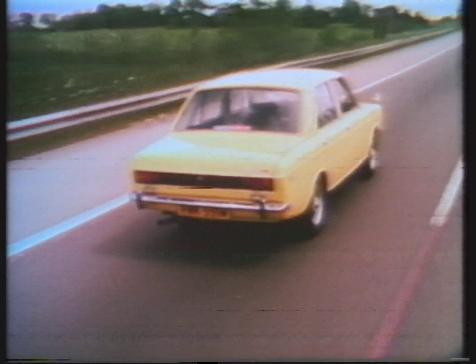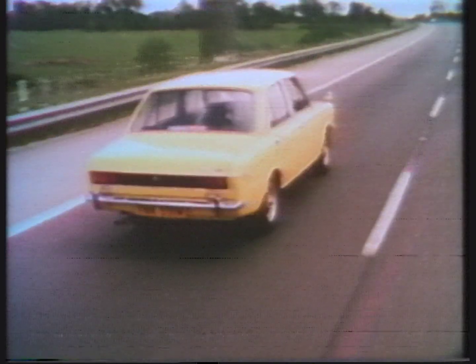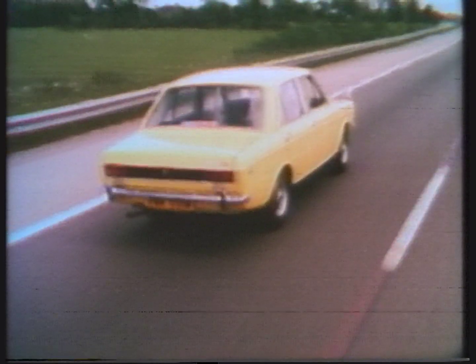Section 3, vibration from the rear. There are 2 basic situations, and neither is felt at the steering wheel. The first is at all speeds over 35 miles per hour. The second is felt at a period between 45 and 55 miles per hour. These are vibrations through floor panels, felt, so to speak, through the seat of the pants.